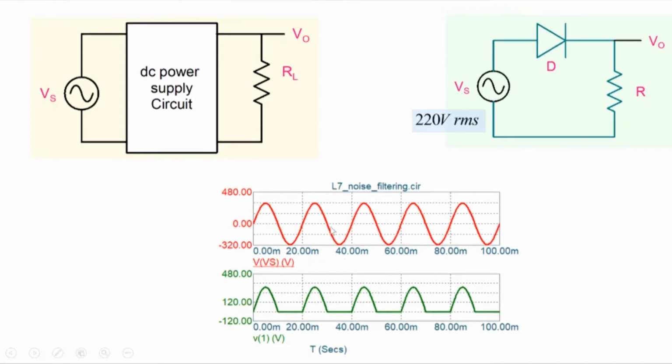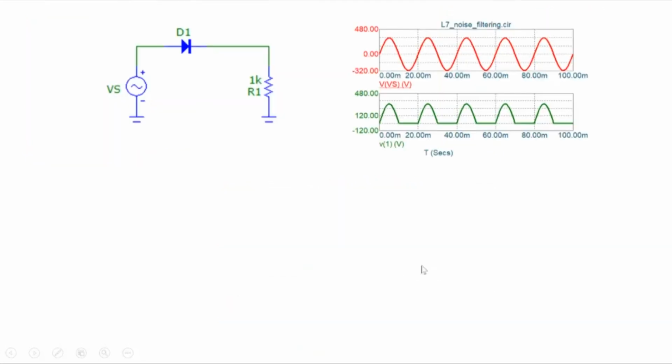So you have an AC here and the diode rectifies it. So we only get the positive cycle here, right? We get a positive cycle, but we want a DC. We want something which is constant, right? So this has rejected the negative part of the waveform, which is good, but we want it to be a constant value here. So for that, note that again through simulation one can illustrate that. So let's say we have a diode here, and this is the waveform that you get, right?